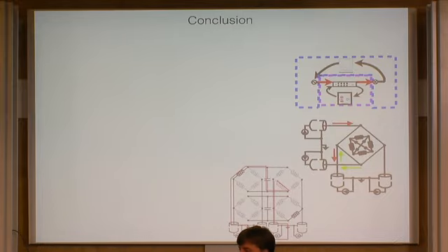I thought your bandwidth and your tone were essentially linked. Yes, but the carrier tone you don't want. So omega kappa, that is roughly equal always, right? For your system. Yes, but the carrier tone you don't want. No, I understand. I'm saying I could have done a Deborah style experiment, but rather than frequency converting from 4 gigahertz to 6 gigahertz, frequency convert from 40 hertz to 4.05 gigahertz. Right. But then, in order to do that, you need a tone that's at 8 gigahertz. No, I could have done that with a 50 megahertz tone. Is that correct? Yes. Okay. Sure.